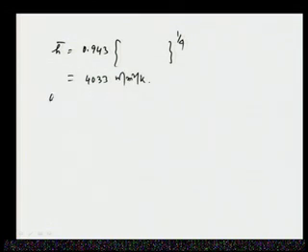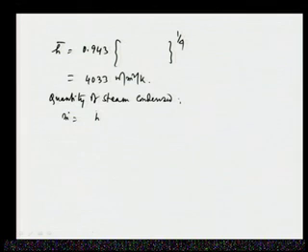So, the quantity of steam condensed, if we try to find out, m dot is equal to H bar into pi dL, that is the surface area of condensation, into delta T, the driving force, divided by LV, the latent heat.